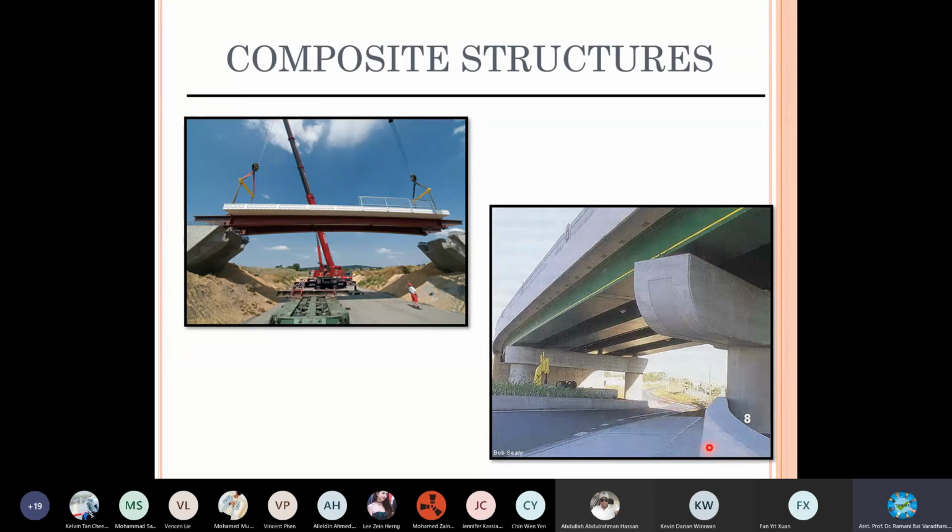Whenever there's a flood, or what if the drainage of this highway is poor, then there is a hike of water, spoiling the member, subsequently spoiling the structure above. So normally they don't go for a steel structure to support a bridge which is susceptible to waterlogging or any type of heavy flooding.